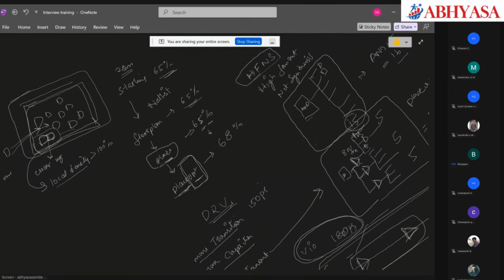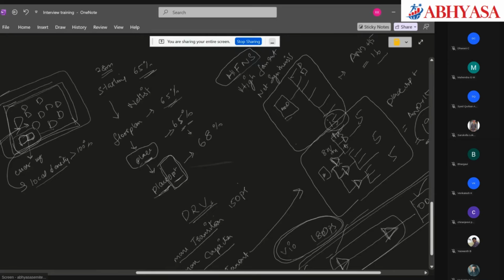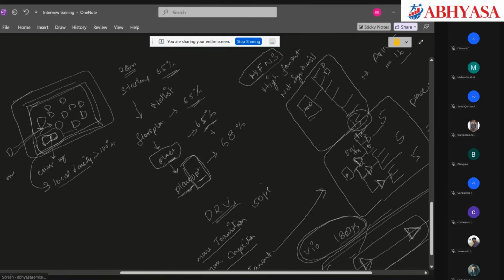Between place stage and place opt stage, did the height and width of the core increase or decrease? Remain the same. Absolutely, it remains the same. But the number of cells that have to sit inside the core has increased, right? So will my utilization increase or decrease? Increases. Absolutely, right?